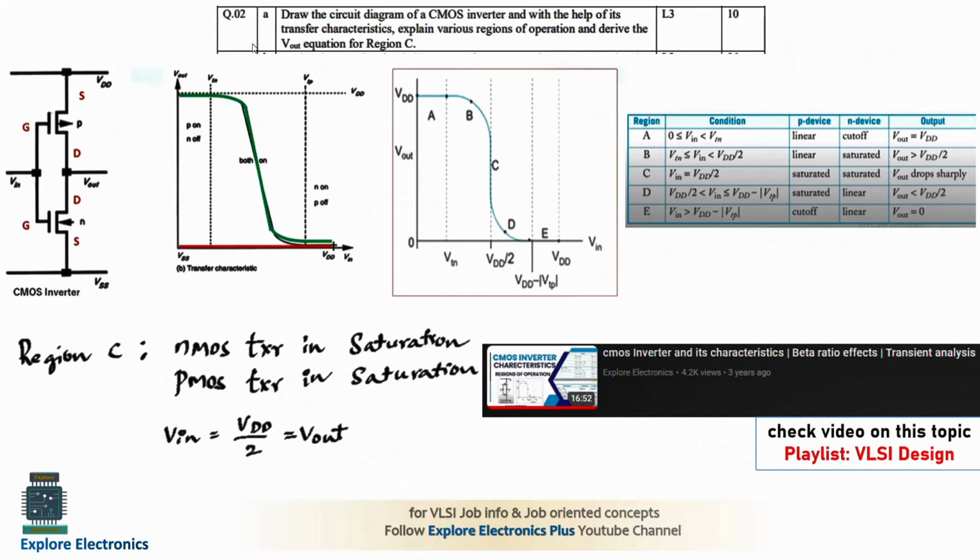Then comes the second question, that is in module 1, the choice question. Here they have asked for the CMOS inverter circuit diagram, and with the help of its transfer characteristics, we need to explain the different regions of operation and derive the Vout equation for region C. So for this, first you need to draw the circuit diagram of the CMOS inverter. This requires one P transistor and one N transistor, and you need to mention clearly the drain, source as well as gate. This is what the circuit is, and you need to draw the transfer characteristics.